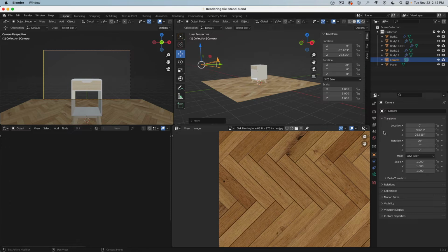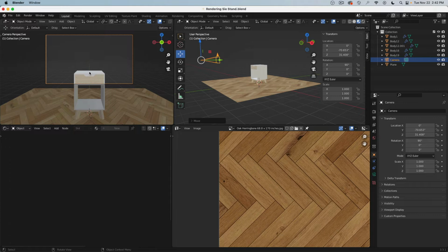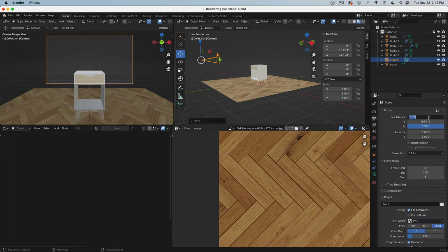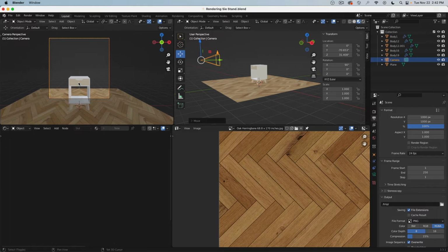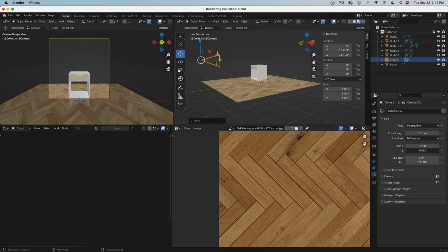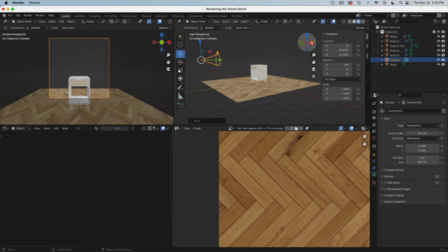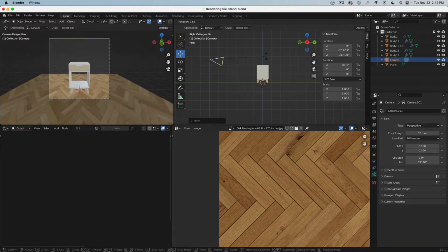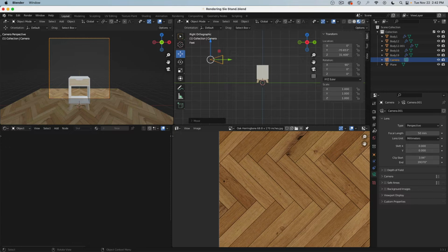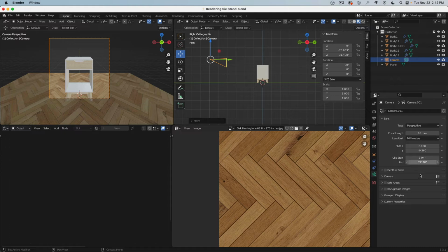There we are. In this camera now I would like to show a little bit of the top of the furniture piece, but now also show the bottom. But before I do this, I want to go to here and set this to 1000 by 1000. So it's a rectangular camera frame. And then with the camera selected, I can move this down. And you see how the image just simply goes up and down. And that is very different than rotating. You see how this perspectively distorts it. That's not very nice. There. Maybe zoom in a little bit.